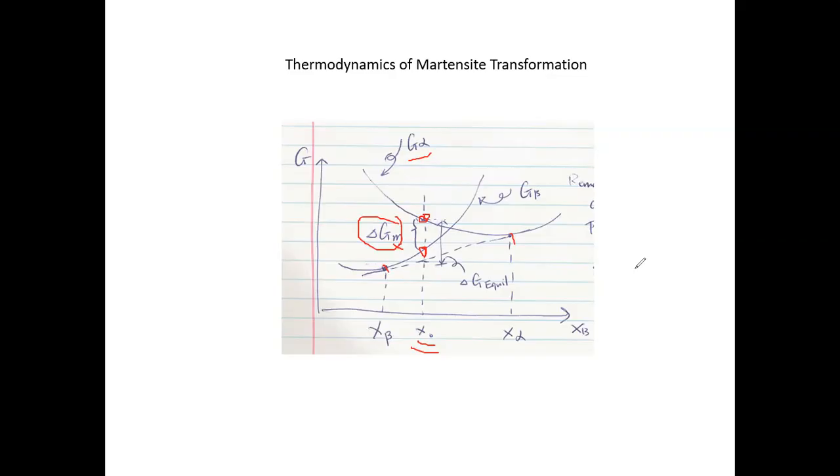This is not going to be a kinetic pathway, but is there a pathway for me to suddenly switch this alpha microstructure to the beta microstructure, right? So that is the key for this to actually occur. If there's no pathway, or along the pathway there's a huge energy barrier, well, then probably you're never going to see this. Does this make sense to everyone?